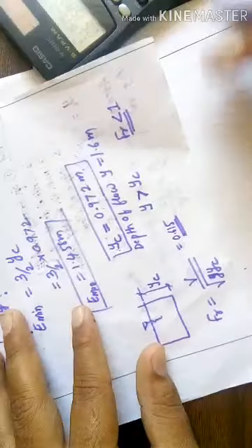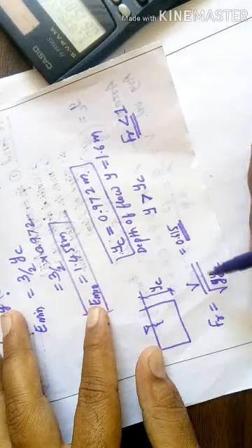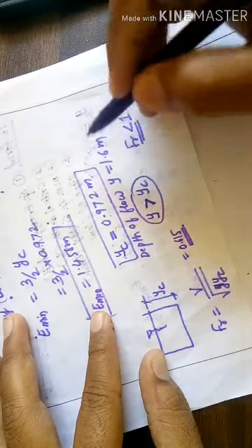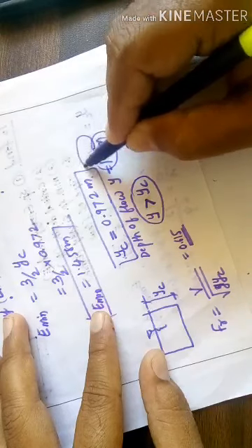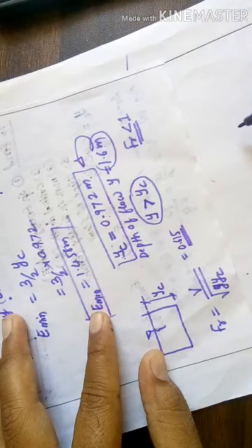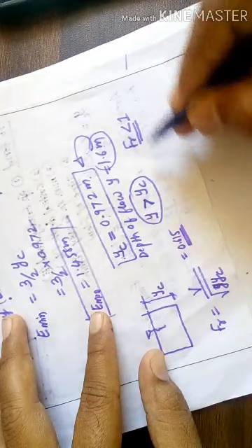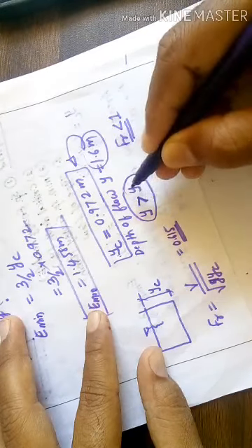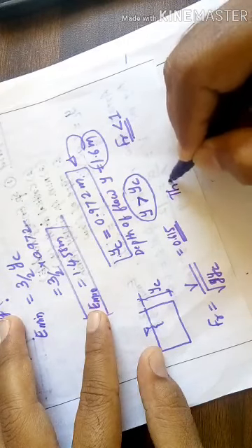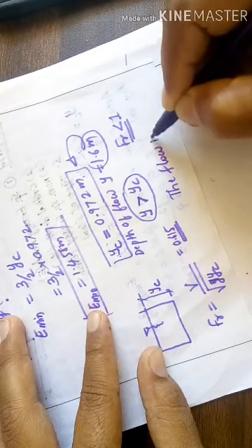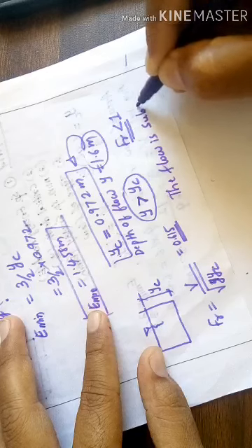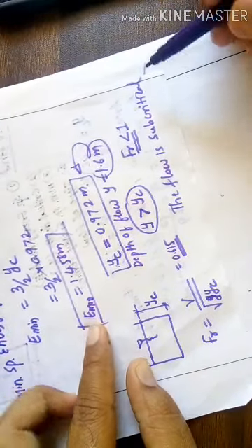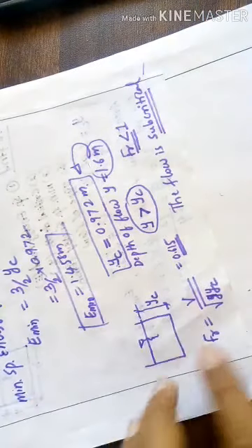You can calculate the Froude number and, based on that, decide what type of flow it is, or compare the depth of flow with the critical depth to decide. Since the Froude number here is less than 1, or the depth of flow in the channel is more than the critical depth, the flow is subcritical. This is the answer.